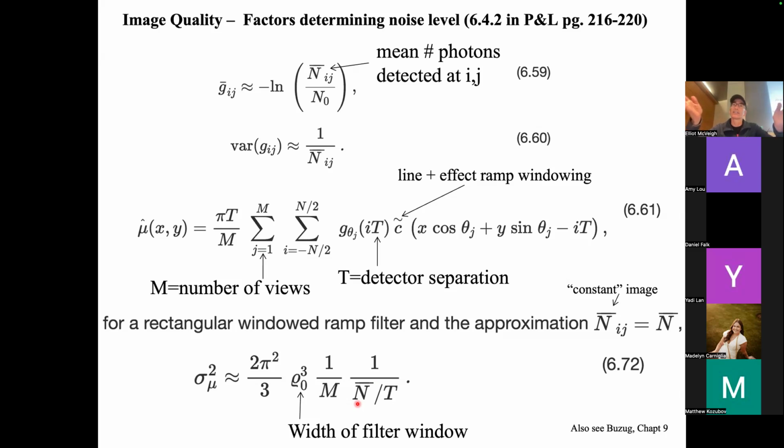So interestingly, the ability to create a picture with that signal to noise doesn't change. So if I'm at a specific sampling rate and my signal to noise doesn't look great, what I can do is just open up by a factor of 2 and then average all those together. And I will get a smoothed, lower noise image. It's a type of smoothing.